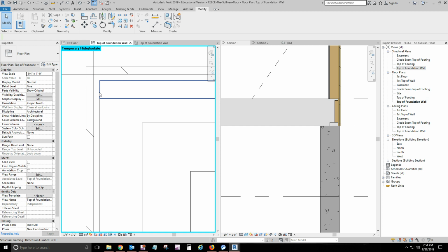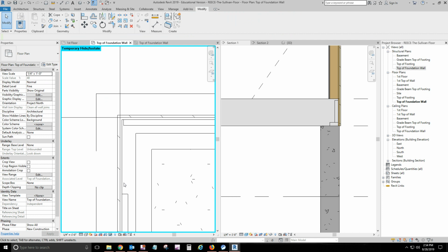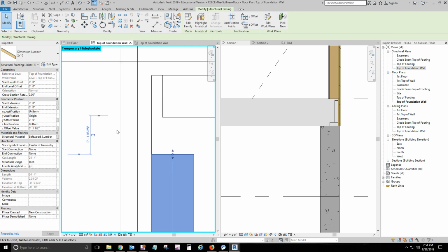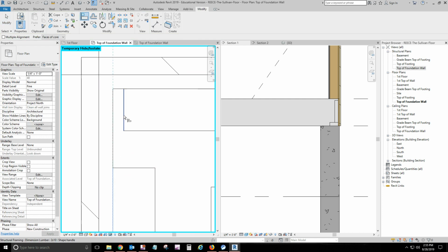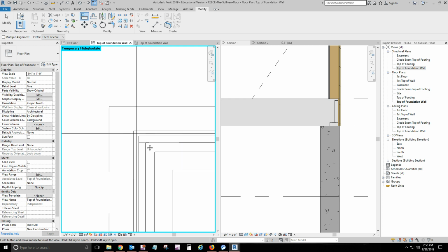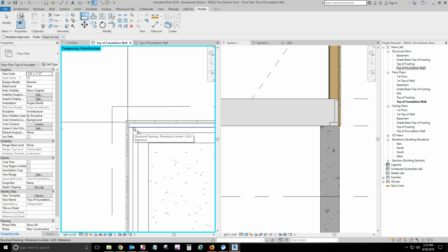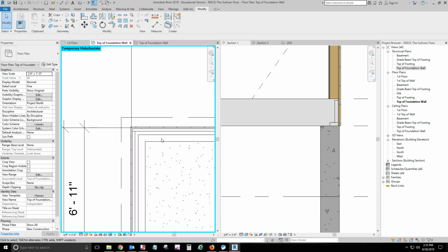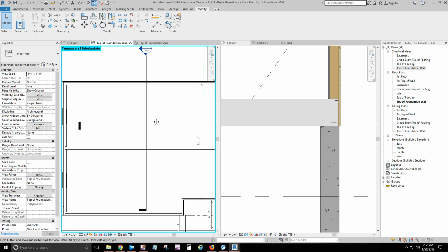All right, so that didn't work. Here's a quicker way to deal with that. This one we know is already aligned to the edge of the wall. So I can go with my alignment and choose the edge of that joist to that one. Then I want to bump the end of this one into the one that goes horizontal. The ones that go left to right, the length of the house, are the ones we bump everything into, because when we put our joists in, they will be attaching to this one.